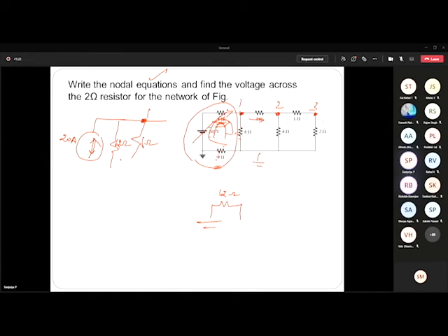Ma'am, it doesn't matter whether the current through the 9 ohm and 3 ohm are in opposite or the same direction, right? We are converting the 3 ohm and 9 ohm to 12 ohm, but the current through them might be in opposite directions? Definitely it's not going to be in the opposite direction. Whatever the current, it's the same direction, the same current. Yes, clockwise, right.